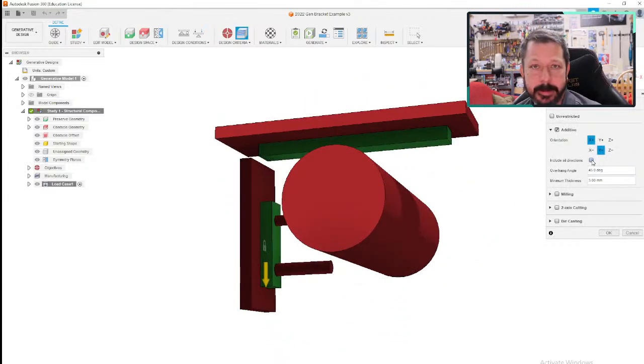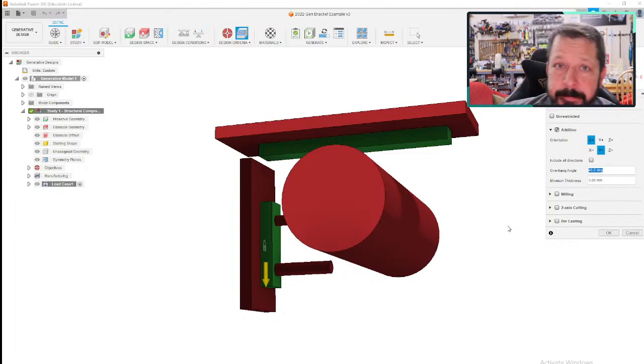Or you could just say, hey, just tumble it in there any way it can go and let it fall where it does. You give it an idea of how steep your overhangs can be, if maybe you don't want to include support at all. So you can tell it, don't give me any overhangs in any of these orientations that I selected that are more than 45 degrees, because I know my printer can print 45 degree overhangs with no support.